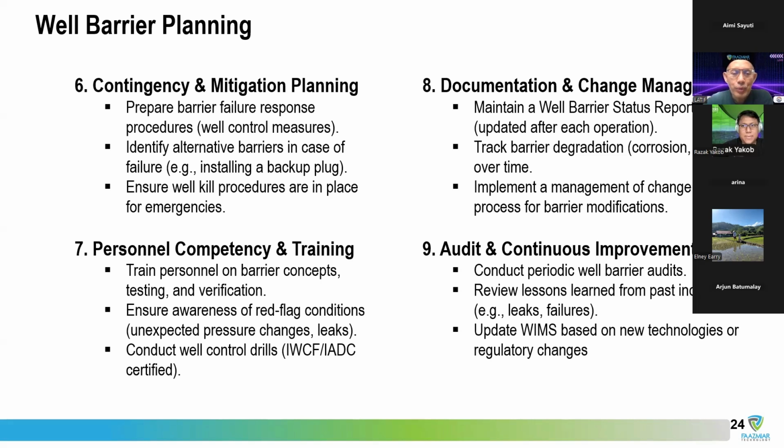Of course, when you talk about this situation, we have different categories, different phases or different times. The drilling phase is different when you have a failure, and a producing well is different. The well intervention and well repair will be different. And when you have your P&A, the contingency plan will be different in terms of managing the hydrocarbon. When you talk about P&A, the well is almost dead. There's no more commercial value, and the gas is all depleted. So we are dealing with losses rather than flow of hydrocarbon. Even so, there is still a requirement to understand the contingency plan in case you have to control the well and then you have losses.